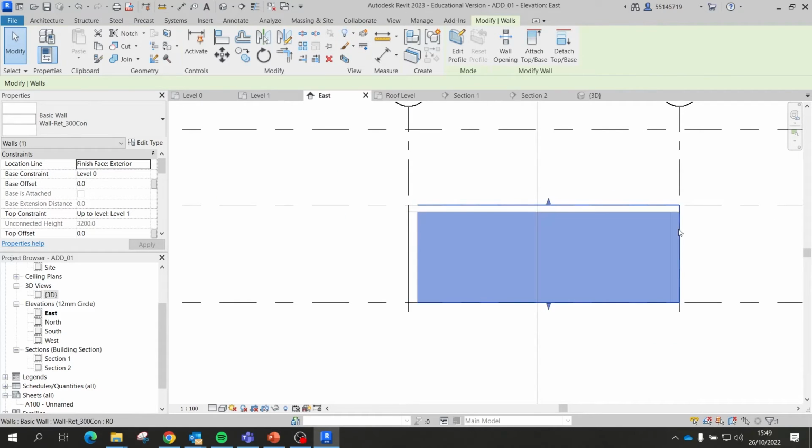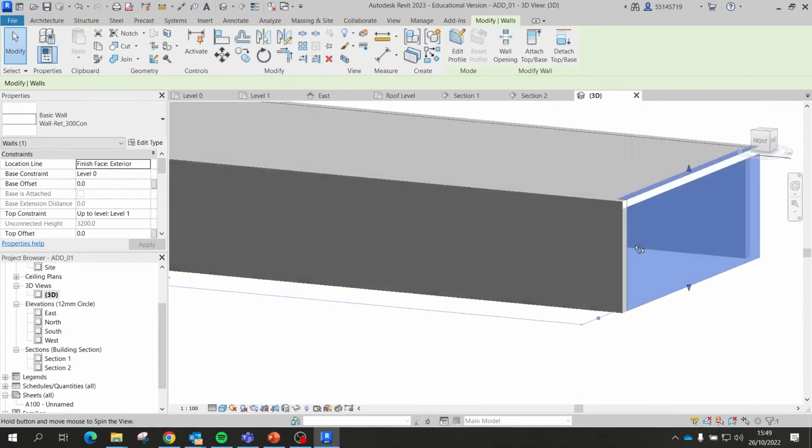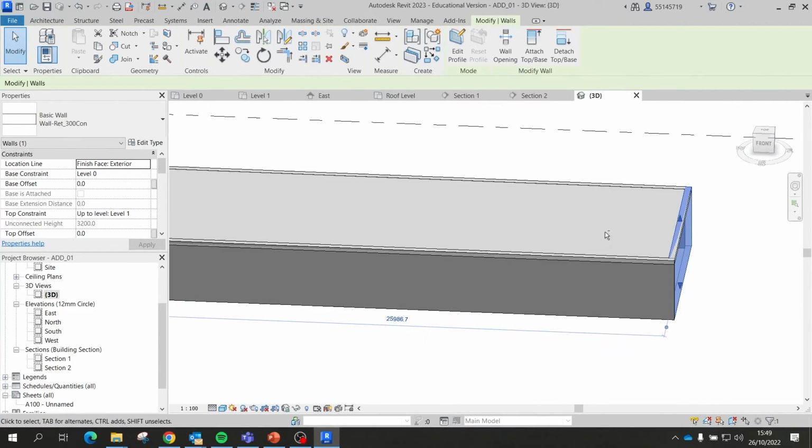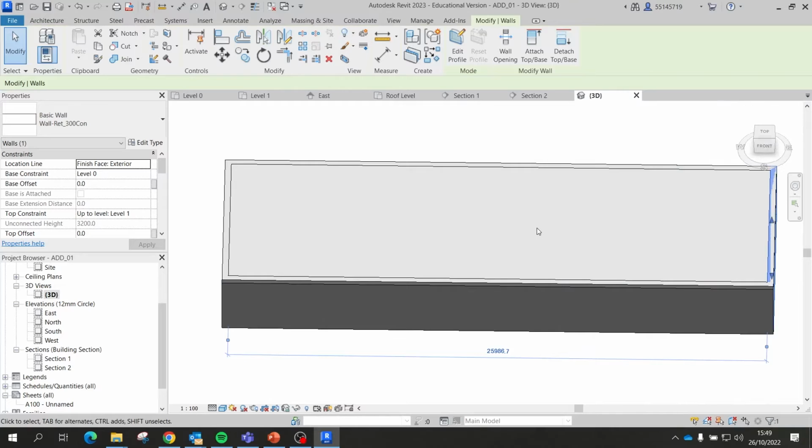If I say no to that message, now I'm still having the walls that are overlapping with the floor plate. Cool. So what I want to do instead, I want to make this a bit more realistic with what's happening in real life. So there will be an offset for the floor plate, and the walls will kind of create that joint moment with the floor plate. So between vertical and horizontal partition, we'll kind of recreate that node.